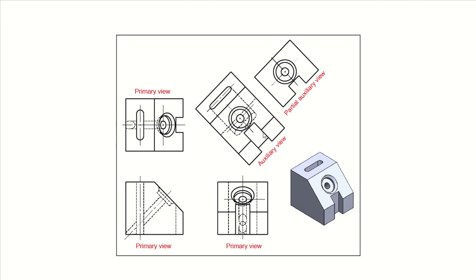All right, on your drawing, where are we going to put this auxiliary view? We're going to put it just straight. So in MET 201, that's what we're trying to draw. So primary, auxiliary view, and your partial auxiliary view is right there. Partial is taking a part out of this, incomplete. This is the full auxiliary view. We're just drawing this part right there, so you can see it clearly. Otherwise, there are too many hidden lines right behind. Some students are forgetting the hidden lines when you draw them, so be careful.